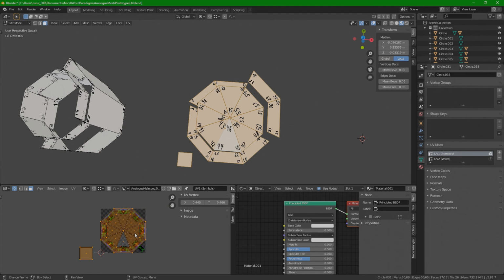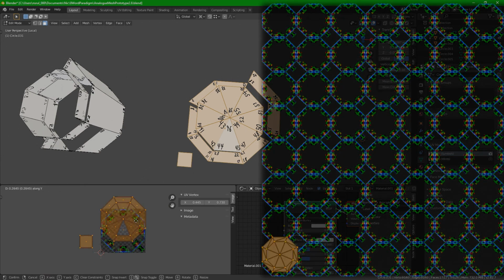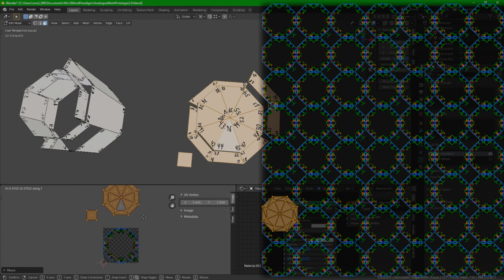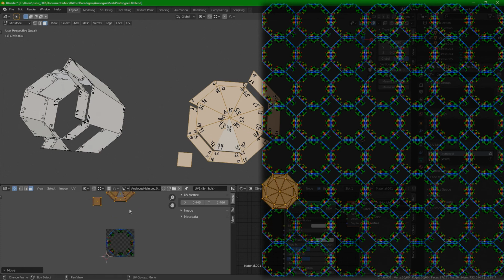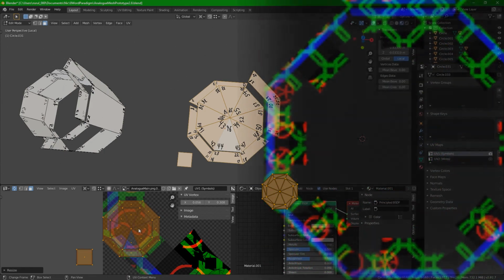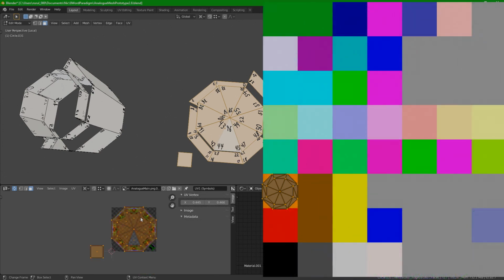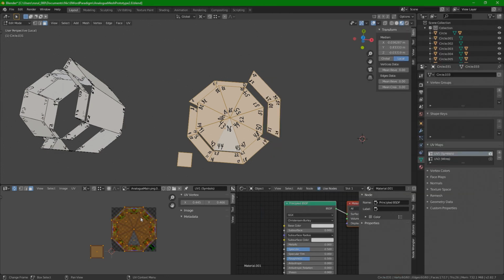And the way this works is that the UVs looking like this and like this are exactly the same. The texture repeats. So it doesn't matter how many whole numbers the UVs are offset by, it will look exactly the same. The thing is, if I move this up by, say, 2 units, and then scale everything down by 1/8, it now lines up with this symbol for alternating current. So symbols are selected by moving the entire UV by whole numbers, which doesn't affect the normal UV projection, it just affects the symbol.